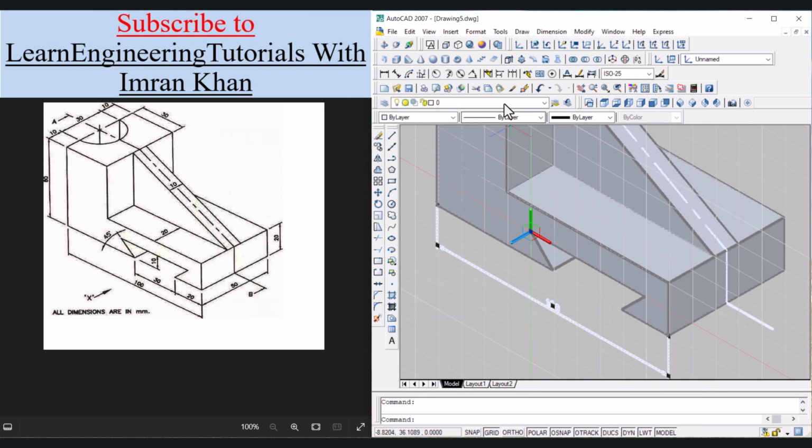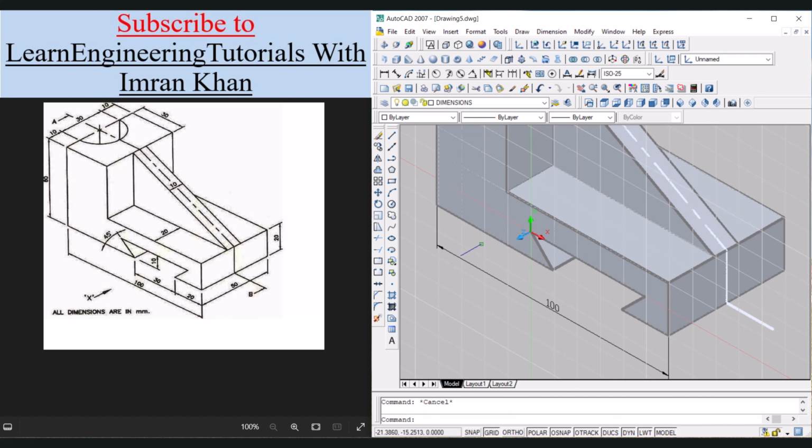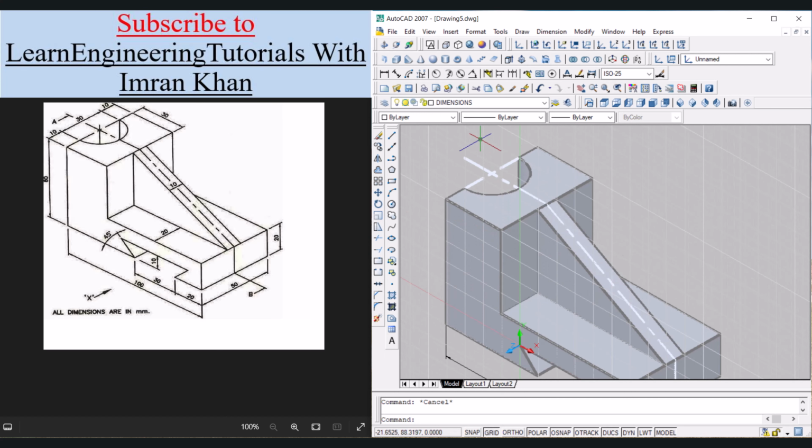Click on this object, click on layer option, click on dimensions. So this dimension has been transferred to dimensions layer. Press escape. Again we are in the 0 or default layer. Click on dimensions to activate that layer, and now we can perform dimensions.